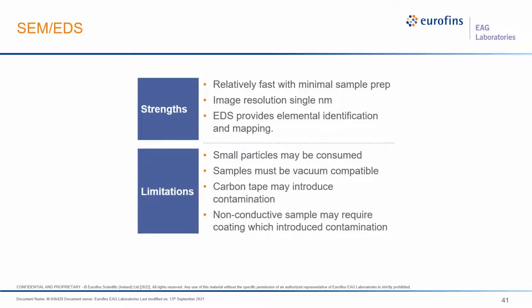SEM EDX, of course, has strengths and limitations, just like any other technique. The strengths are that it's really fast, with minimal to no sample prep. Imaging resolution can go down to single nanometers, and EDX provides elemental identification. And of course, if you want mapping, we can get mapping information as well.